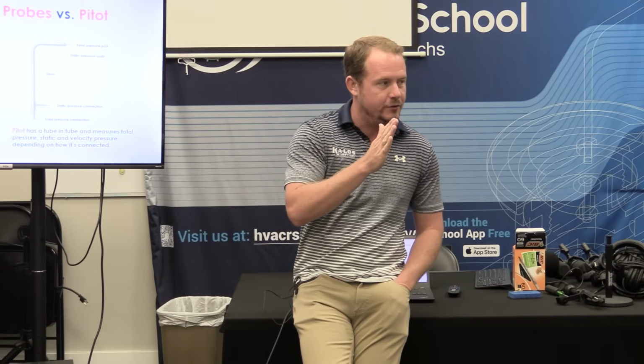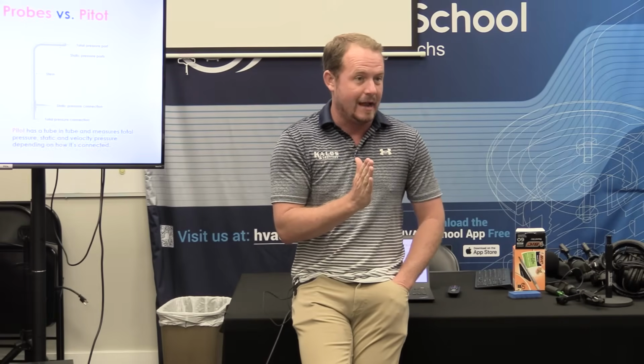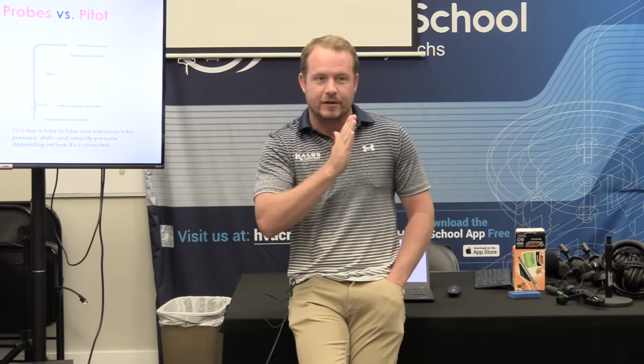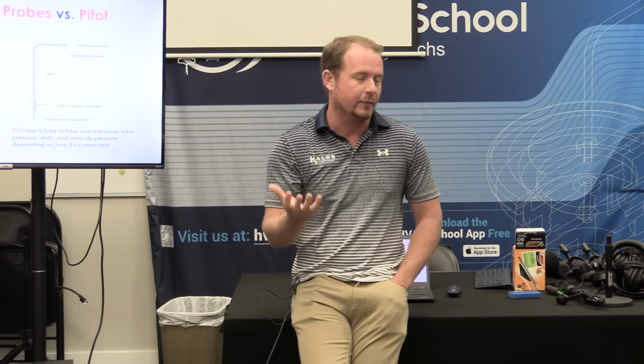Make sense? Every measurement is kind of a differential pressure measurement. It's just a question of what it's comparing to. Is it comparing to a real-time atmospheric measurement, or is it comparing to some measurement that you zeroed to previously? It's always measuring against something else. And again, the reason is that there is no such thing as zero pressure. What we call zero pressure is actually just 14.7 psia or thereabouts, but even that fluctuates.